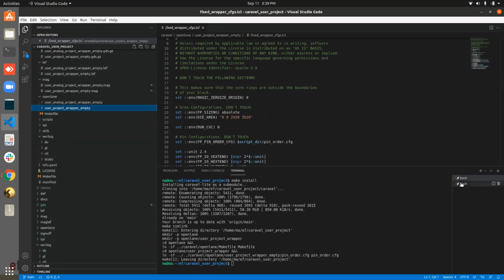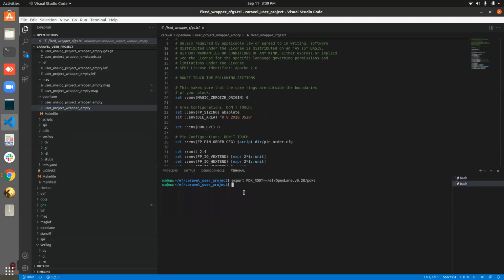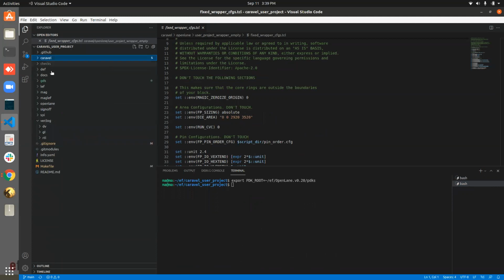The next step is you will need to run the full chip simulation to make sure that your design works within the context of Caravel. You need to have the RISC-V toolchain installed, and you need to have iVerilog installed. If you don't want to install them locally, we provide a Dockerized version for them.